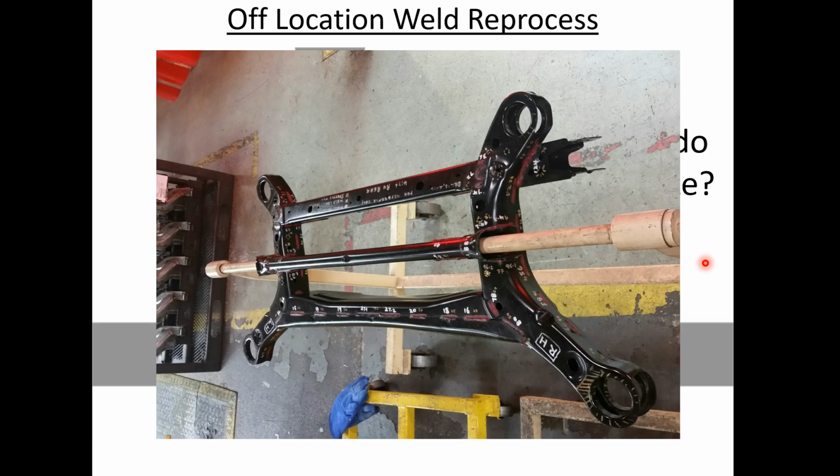Right? And here's another very important tidbit that goes across the board for almost everything. You never put weld metal where weld metal's not supposed to be. Ever, ever, ever. There are structural, metallurgical, and strength changes that happen to these materials when they get hot. And you putting welds, or thinking, oh, more is better, and I'm just going to take these two welds and connect them together. No. Always remember something behind all of this. One day, this component might be subject to crash tests, not just in testing, but in the field. One of the things engine cradles have done for us over the years is greatly increase the safety of a vehicle, because it gives our bodies more time to decelerate, how it crushes, how they want the engine to roll and end up underneath your feet. So there's a whole bunch of technology behind this.